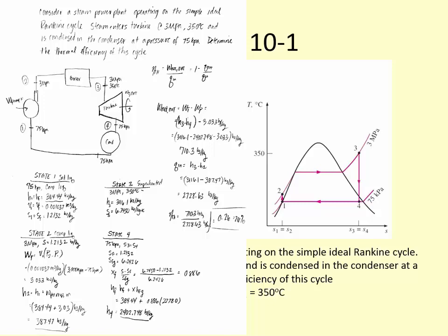Because I already know the temperature and pressure, and it's a superheated vapor. Yeah, so the state's fixed there. With this one, I need to find the quality. And this is the part that people have the most trouble with on exams, I've noticed. This step here, having a known property value, using it to find the quality, using that quality to find your unknown property value. So anytime you end up in the liquid vapor region, that's the procedure you need to follow if it's not already fixed, like if quality is not given in the problem or something like that. Okay, we're going to move along.